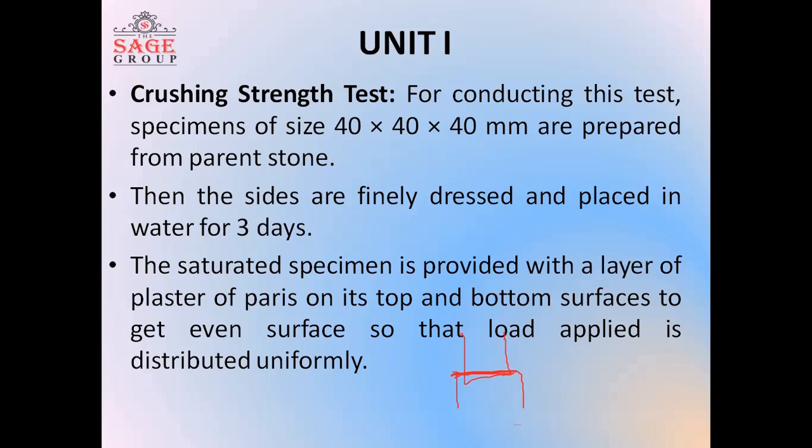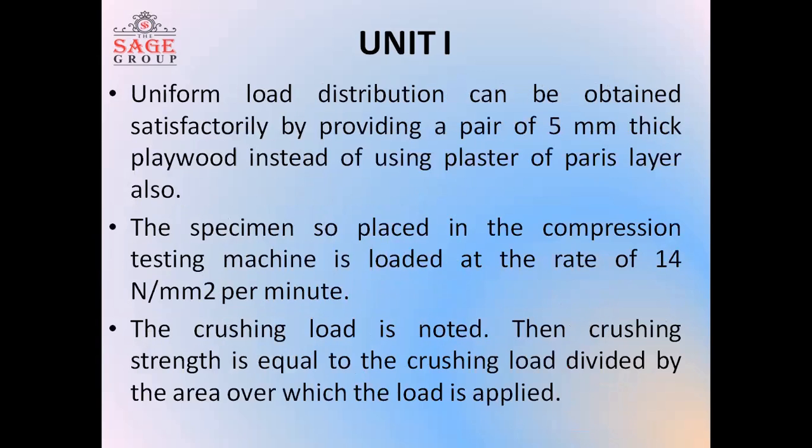If the stone has an irregular shape and the load is not distributed uniformly, then the exact or accurate strength of the stone cannot be obtained.